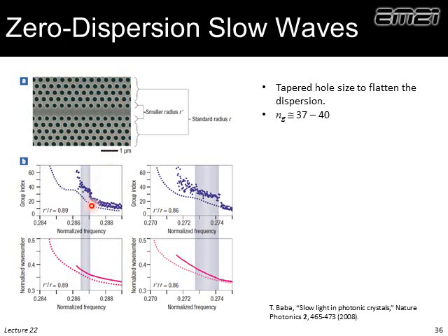And if we look at the group index versus frequency, what we can see is that it's a rather straight line in this region of being a slow wave. See a nice straight line over here. Again, here we have less dispersion, but over a wider bandwidth. And here we have more dispersion over a narrower bandwidth. So we see our typical trade-off, but we also see that this is rather flattened. And by just engineering this taper, we can make those flatter or less flat.